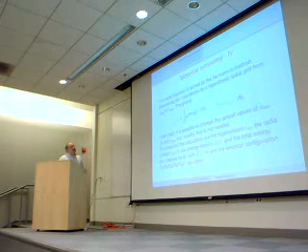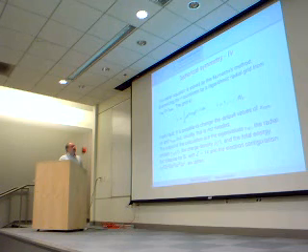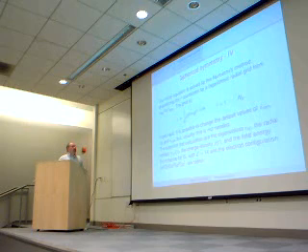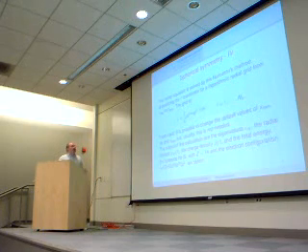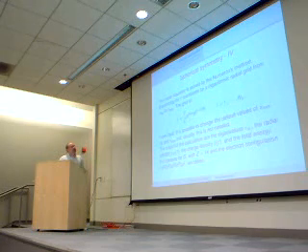From input, you can define the value of x min and delta x, and also of r max, the maximum r. But usually the defaults are quite well tested, and we will not change these values. However, if you doubt that your result is converged with respect to the mesh, these are the 3 parameters in the input that you can control.